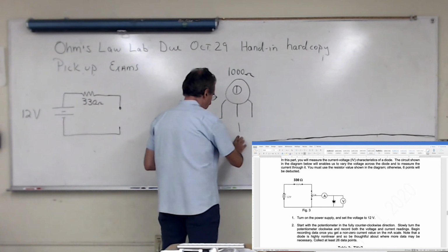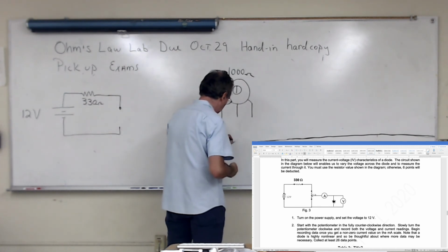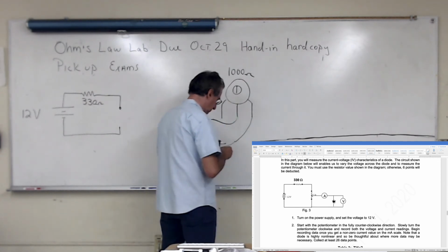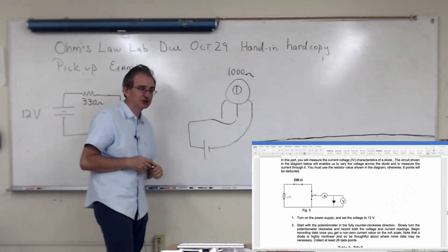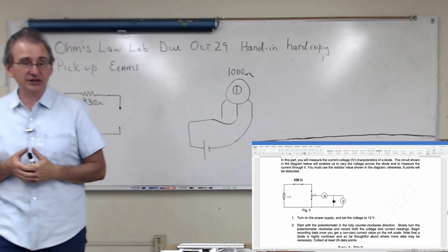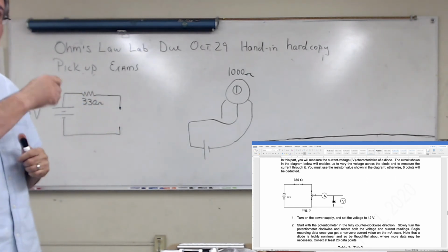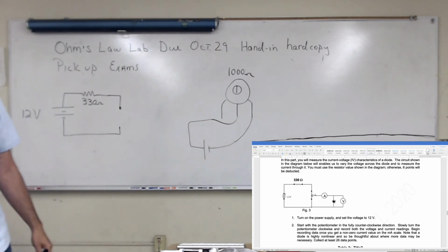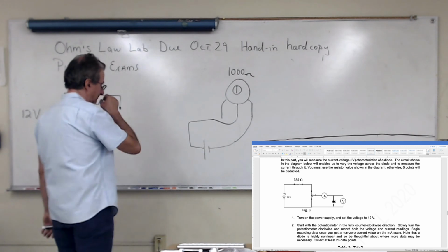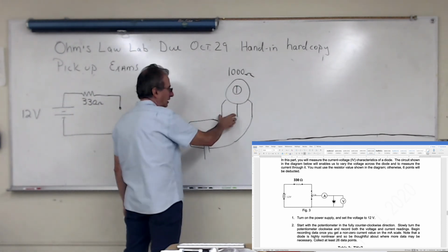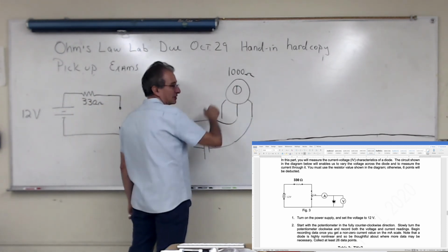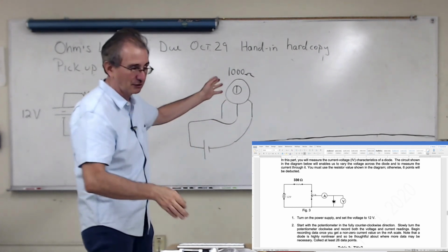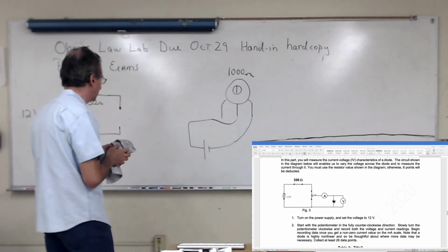If you connect your battery to these two, then you have a resistance that changes as you change the dial. It'll go from 1,000 to 0. If these two go up as you rotate clockwise, then these two will go down as you rotate clockwise. Clockwise meaning assuming you're facing it, okay.